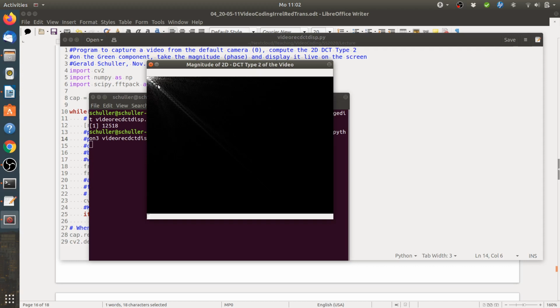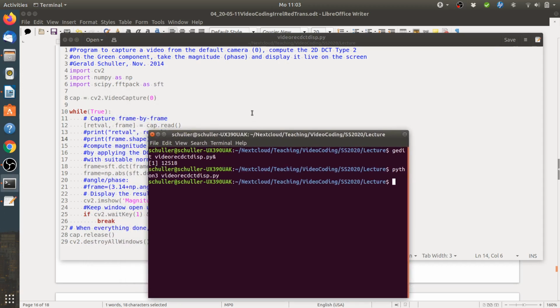And also observe here I'm not using the decomposition into 8x8 pixel blocks, but I'm applying the DCT to the entire frame. And this has the advantage for this demo that you see this frequency domain in more detail, right? So here we now have 640 columns and 480 rows and a corresponding size for the DCT. Right, so Q quits it.